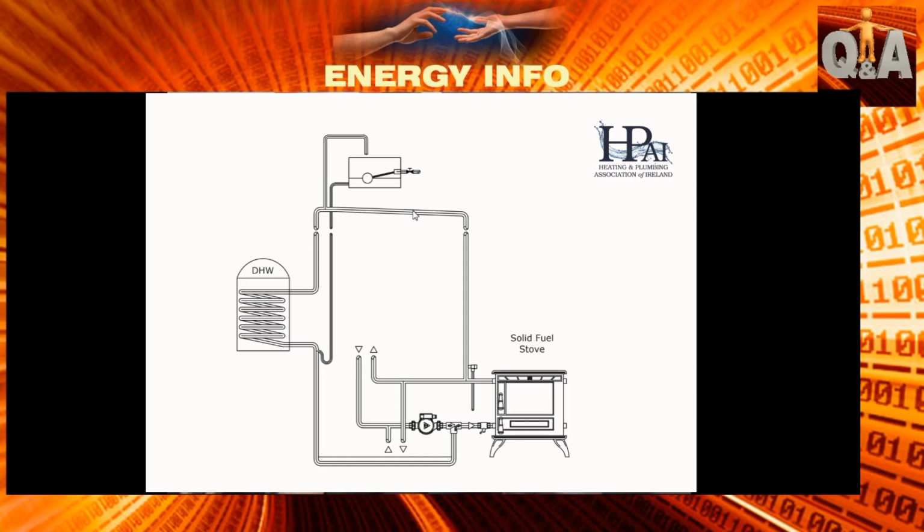And just to add to it as well, lads, this is very close to the system that I have at home. The only added extra is that I have solar, and I had solar in this as well. And as Harry said, it did reverse. It did start reversing out on me because the solar was heating the cylinder, and it started reversing back out and back up into the cylinder and losing heat. It was losing an average of about 40 degrees a day because it wasn't insulated properly.